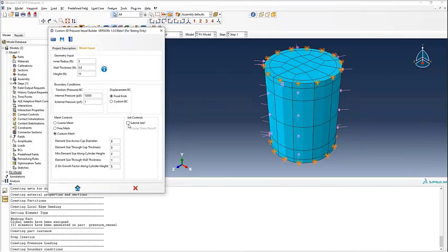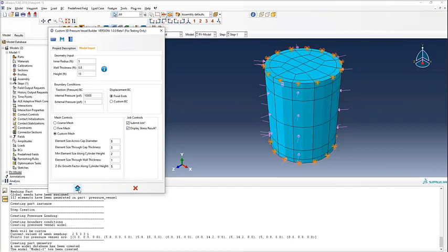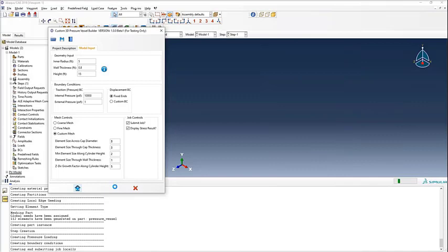So we can see it as a very coarse mesh, something you obviously aren't going to use in an analysis per se, but for this demo, it's very practical because it will run quickly and allow us to show the other parts of the GUI here. So we submit our job. If we look down below in the message area, it's gone through the processing. It's now creating and submitting the job locally. And now it's in that wait for completion area of the kernel script.